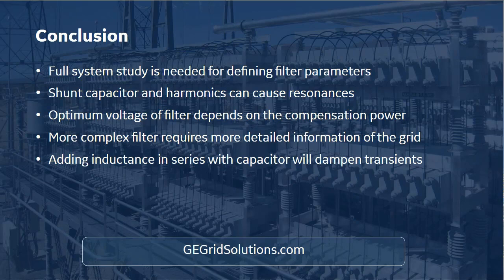If we have a very complex filter, for example a double tuned filter, or a C-type filter, or anything more complex, or many single tuned filters connected in the same system, we have to know a lot because we have the resonance issues and so on.